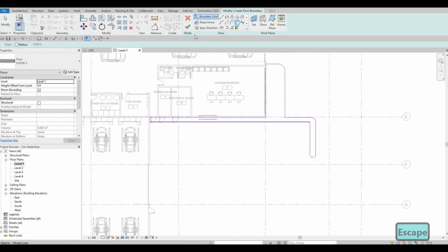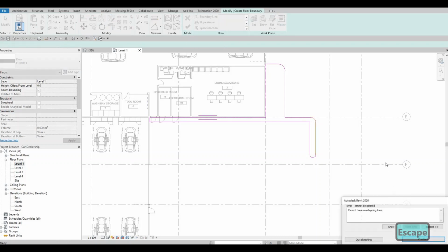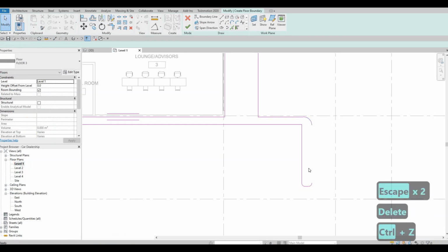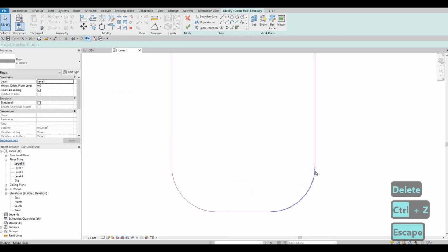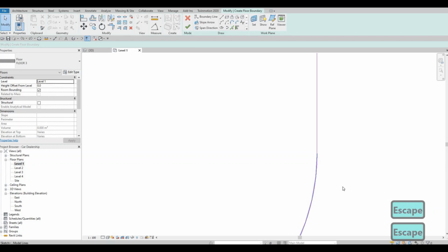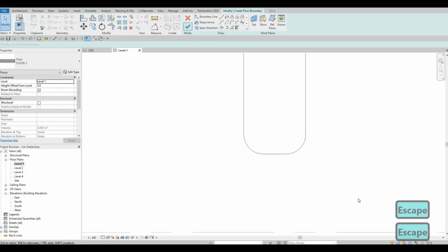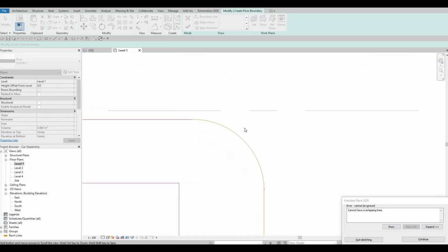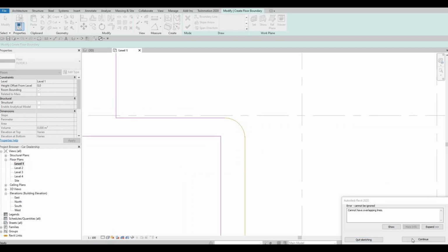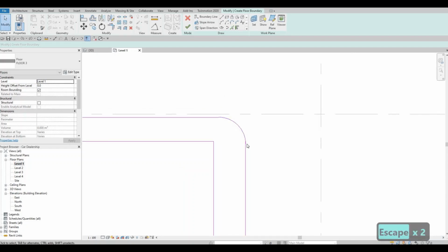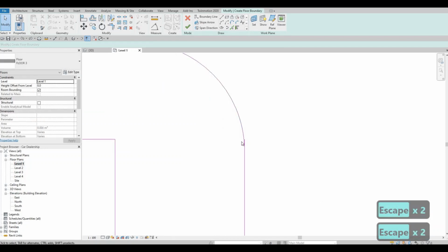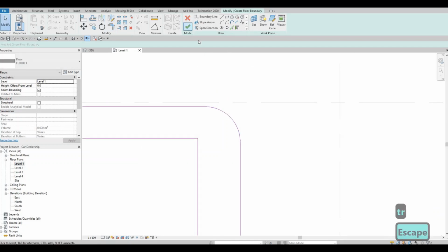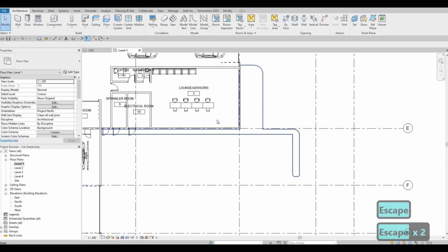So I want this first, so let's click finish, and then here it's saying that we have something right here that is probably overlapping. I'm gonna click finish again and then show what's the issue with this. Cannot have overlapping lines, so we need to investigate which is the one that's overlapping. So we need to trim and extend this part. There we go. Let's try it again, and that cleans that up.